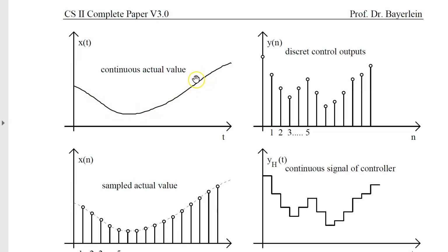In signal theory, in digital signal systems, it is easy. You know the Shannon theorem: look for the highest signal frequency, then double this, and then you have a good minimum sampling frequency of your digital system. This works in signal theory, but in control systems, we have no signals. We have process output values, but how large is the frequency of this signal? You don't know it, because normally these are constant or slow changing values.